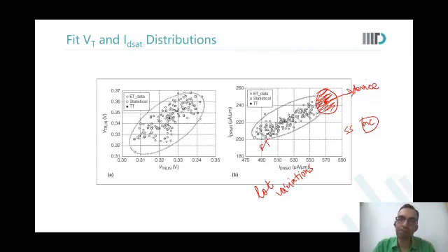Doping, L effective, W effective, stuff like that. You vary all those parameters for different devices and randomly place those variations on different devices. Then when you simulate, you get this red shaded circle around that lot point. It is the sample of transistors that could be manufactured on that particular lot.